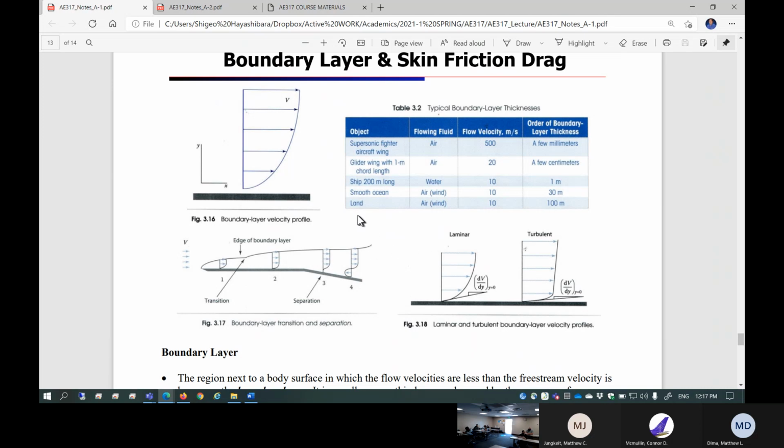This is a boundary layer developed on a flat plate. Flat plate means there is no pressure gradient. Shape is flat. You can actually simulate a non-zero pressure gradient surface, such as when you design your cross-section of a wing, called an airfoil. It comes with a certain shape on the top surface and bottom surface. That is not a flat plate. Of course, that shape can be built into the model, but every model of boundary layer starts from the flat plate model.